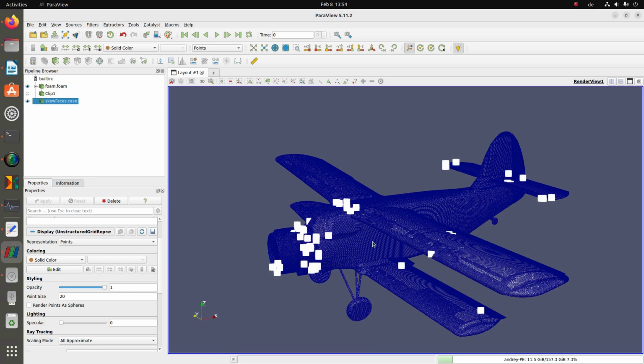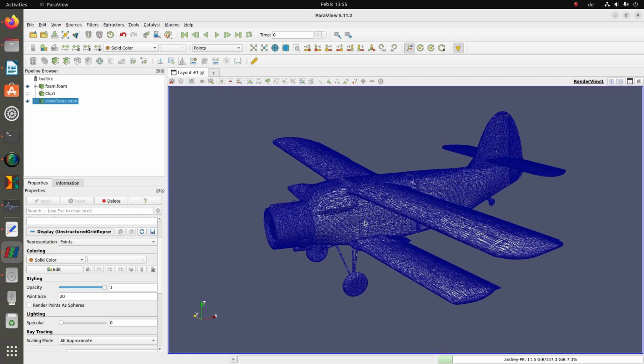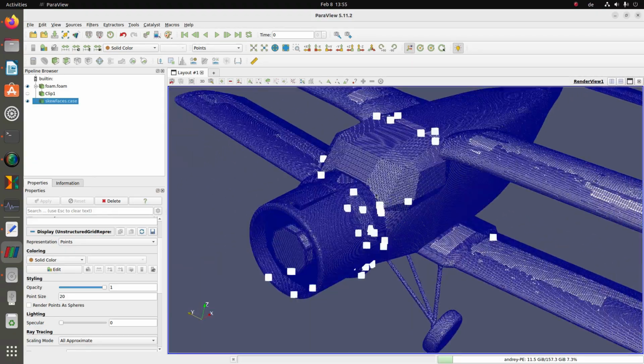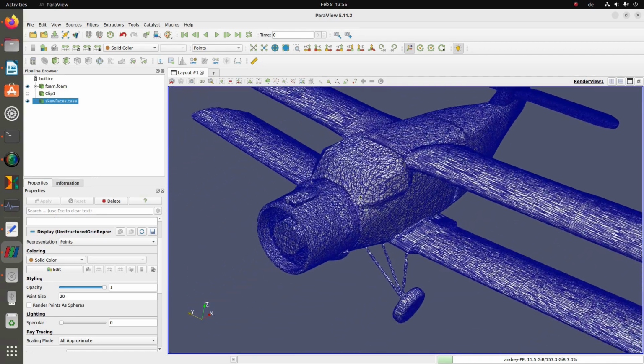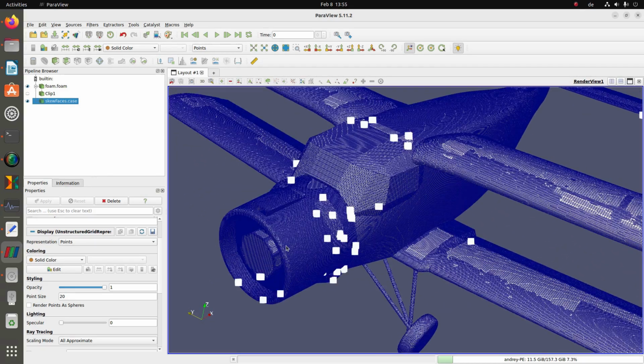You see, all cells are in different places. Normally, if the cells are at one boundary, you can change the quality by minimizing the cell size. In our case, the cells with the bad skewness are located at different boundaries. Some of them on fuselage, some on rudder, some on flaps and elevator, as well as on motor fin or motor section. Therefore, the only way to improve something here is to change the mesh quality settings.